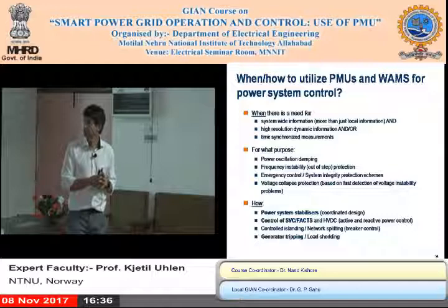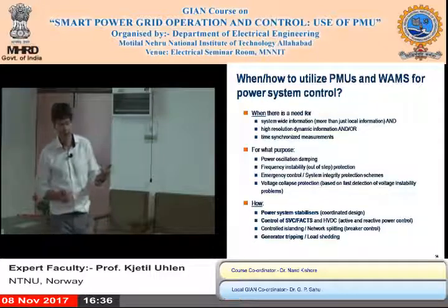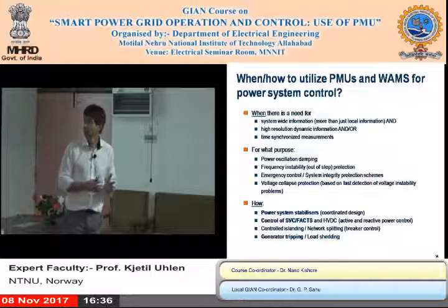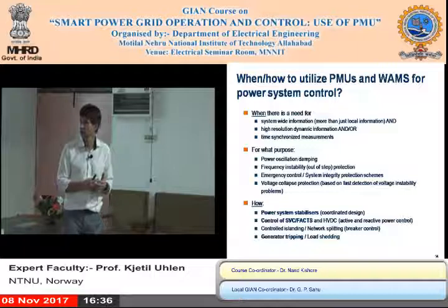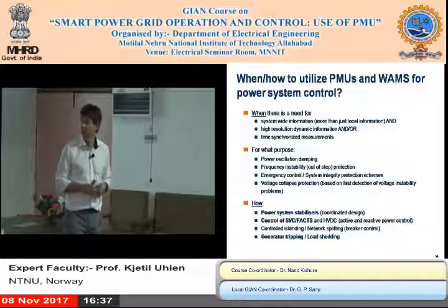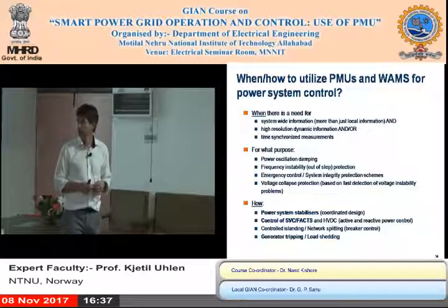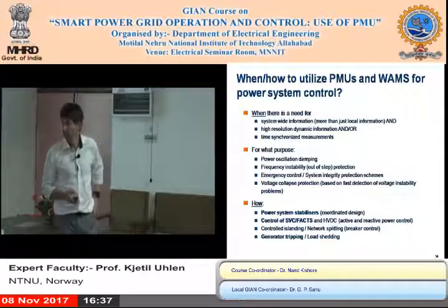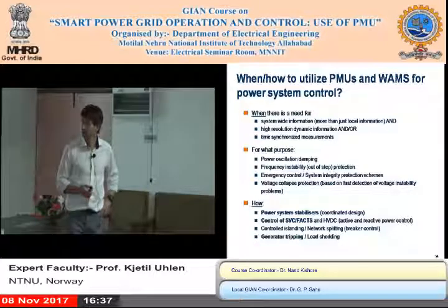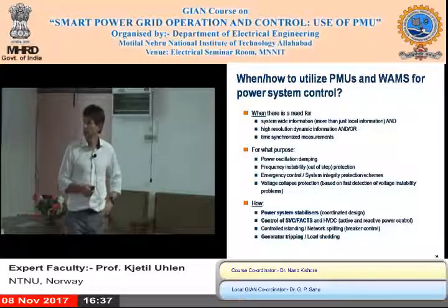But there also should be a requirement for high resolution dynamic information, otherwise you could use SCADA measurements, for example. So there must be a need for the high resolution data. Or if you need time synchronized measurement, of course, then you have a reason to look into PMUs for control as well.